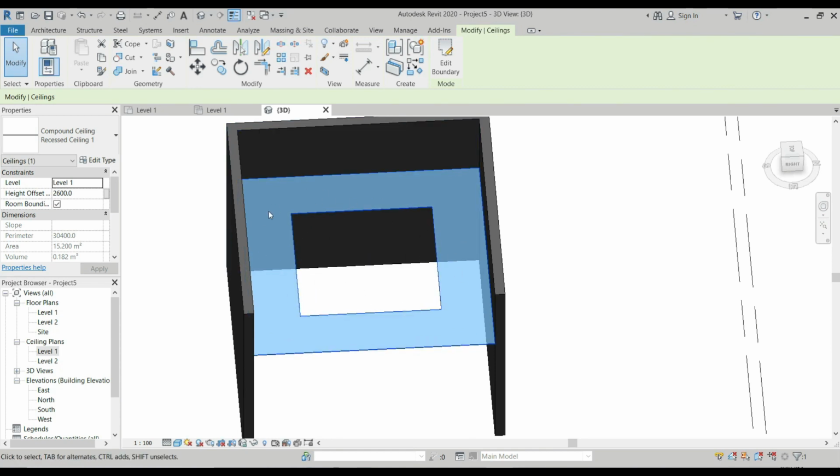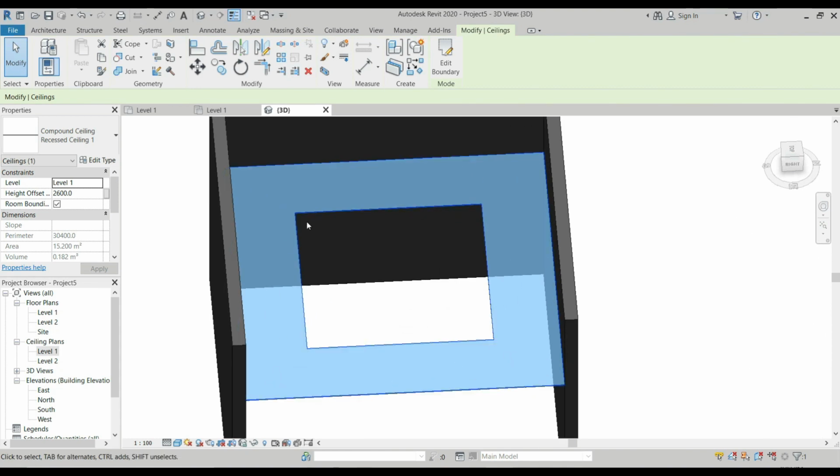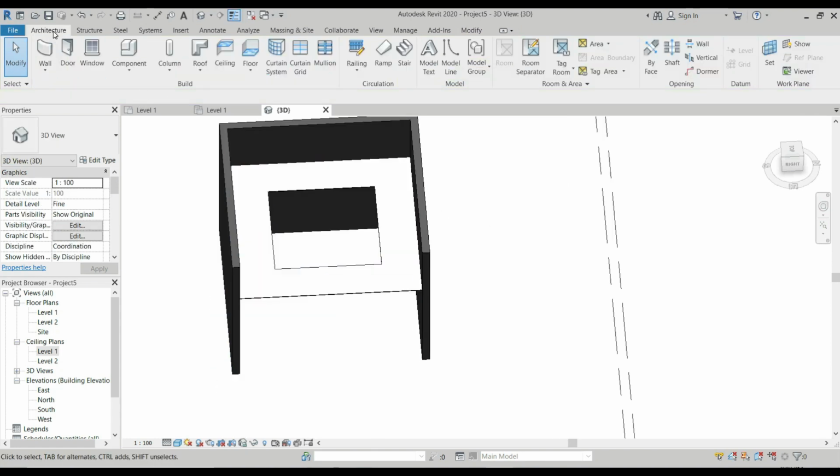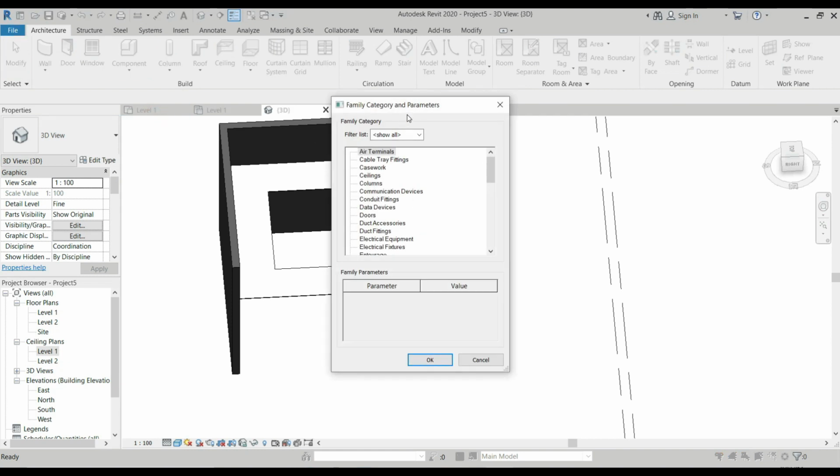on our ceiling. So to do the wall here, for the recess, for the cove, let's go back here in architecture, then click the component and click the modeling place. So here in the modeling place, you will see a window where you can choose the categories and parameters for your model. Since our model will be on the ceiling, we will click these ceilings.